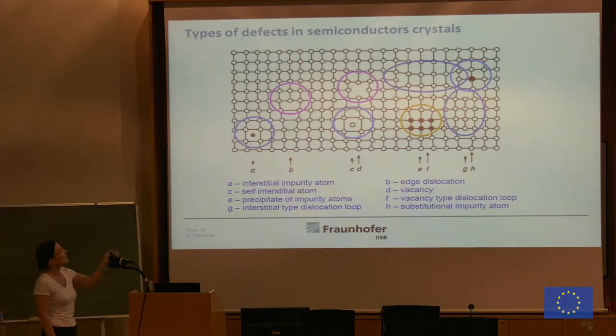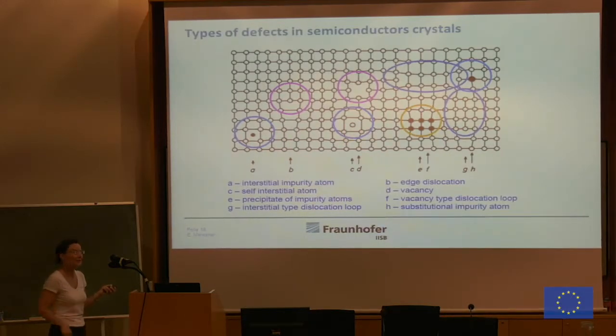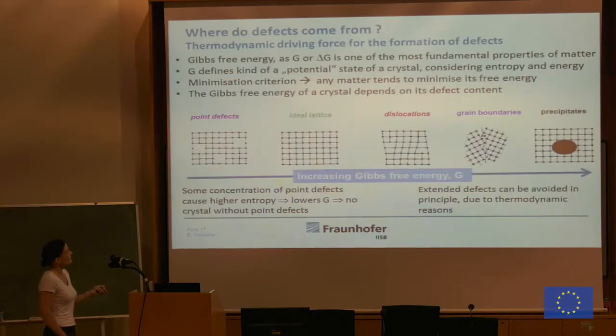If you introduce an extra layer, which is, for example, an edge dislocation, then also the surrounding has to adapt to that place in some way. So you have elastic deformation, whereas the dislocation represents a plastic deformation place. And so you have all these types of defects that we have to deal with.